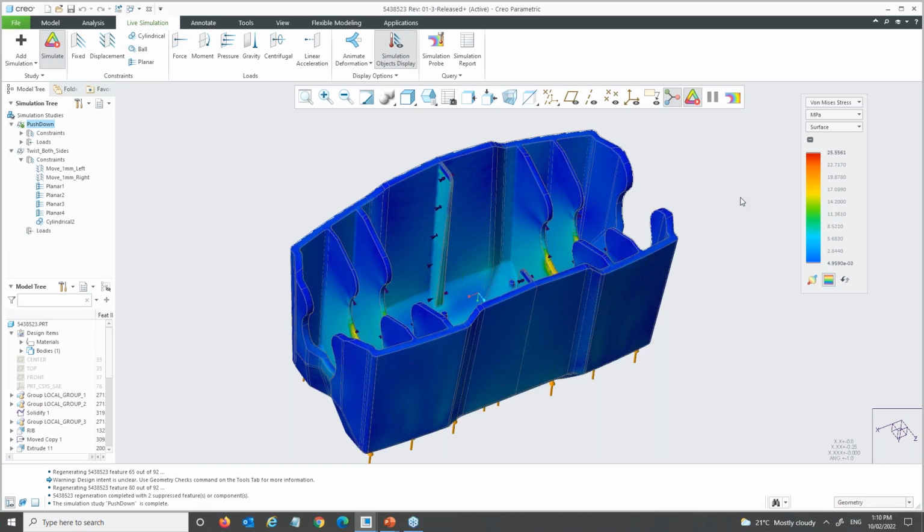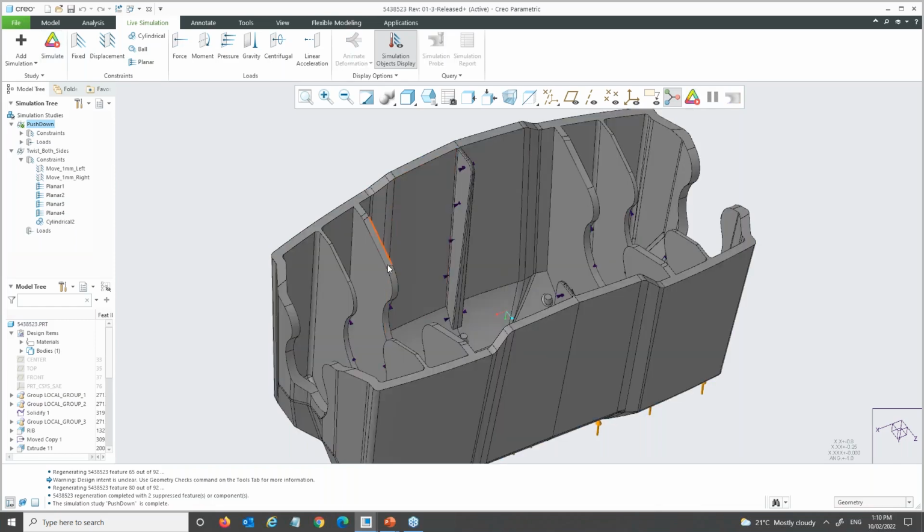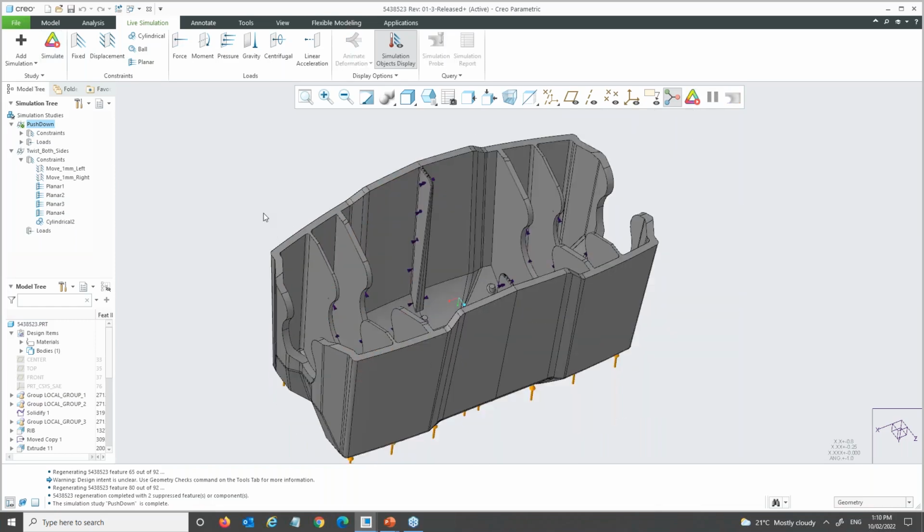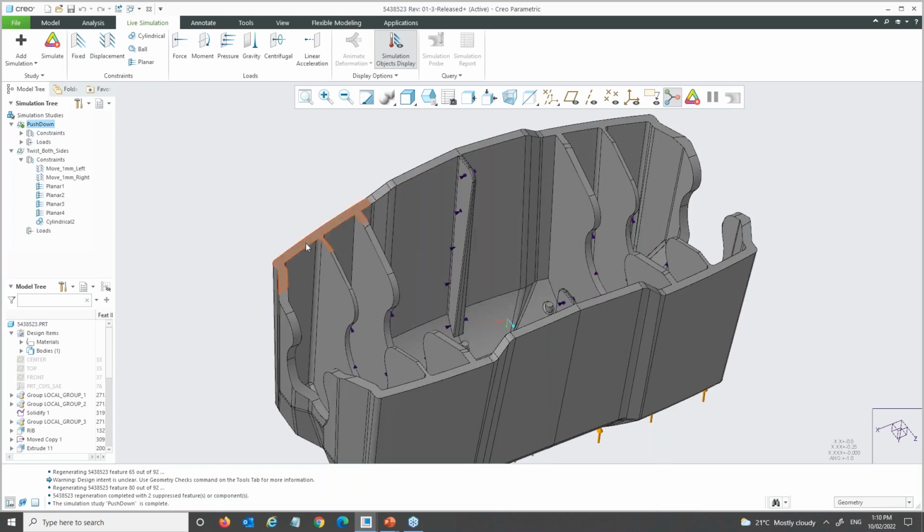All right. Having done that structurally, this model now sounds okay to me. The next question for me is, what about the moldability? I know there are some slender ribs here. My concern now is, because it's really thin, whether it will be fully filled in the mold, or if there will be a shortfall, a weld line or air traps.